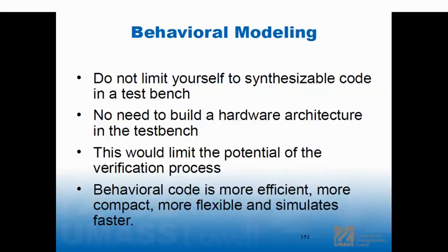So we're writing behavioral modeling here to make the job, I'll say easier, but to give us more capacity for what we need to do in the simulator. We get another piece of that. Because remember, when we talk about simulators, we say behavioral code runs faster in the simulator than RTL code. And the reason for that is it has less detail. And remember that RTL code runs faster than gate level code because RTL code has less detail than the gate level code. So the designer doesn't have to worry about the architecture, but the simulator also doesn't have to worry about building things in the structure of the code. So we speed up in two directions.